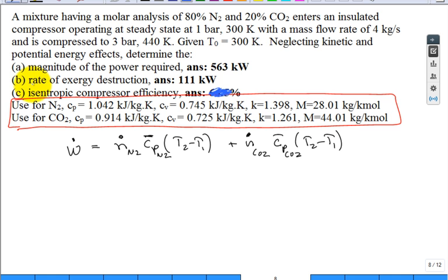How about for part B, the rate of exergy destruction? Well, it was all down to sigma dot, and I'm going to put it on a mass flow rate basis. It doesn't really matter, does it? Mass flow rate of the nitrogen, and then we had C sub P of the nitrogen, natural log of T2 over T1 minus R natural log of 3.